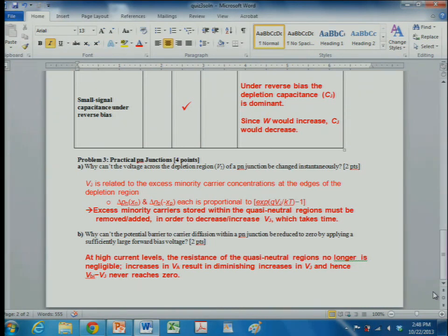Oh, okay, capacitance. Well, yeah, that's exactly how we model it. We model it as a capacitance, right? That you have to move charge. To change the voltage on the junction, you actually have to add and subtract charge. That's exactly the capacitance effect, the small signal capacitance effect. So technically, that's the same reason.